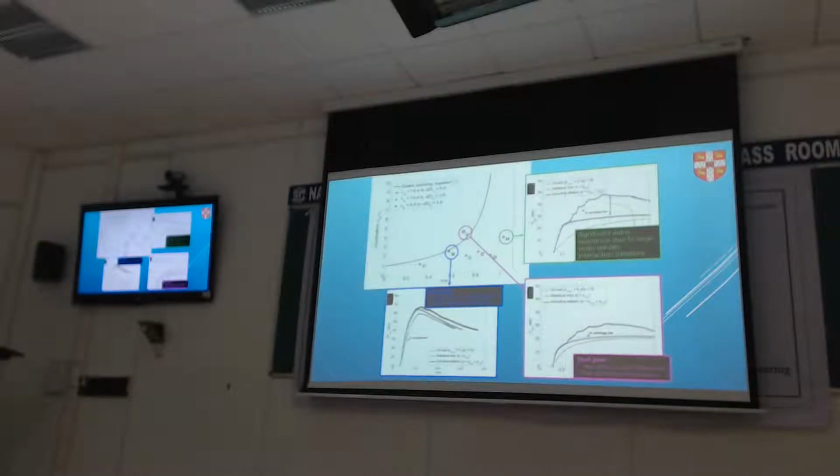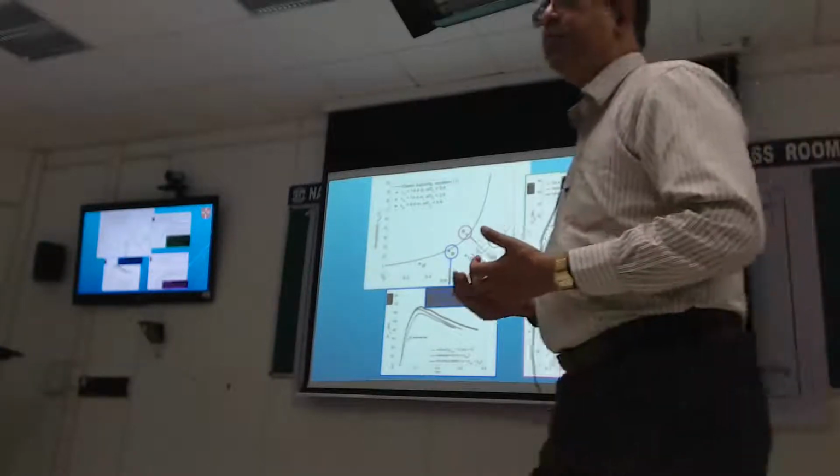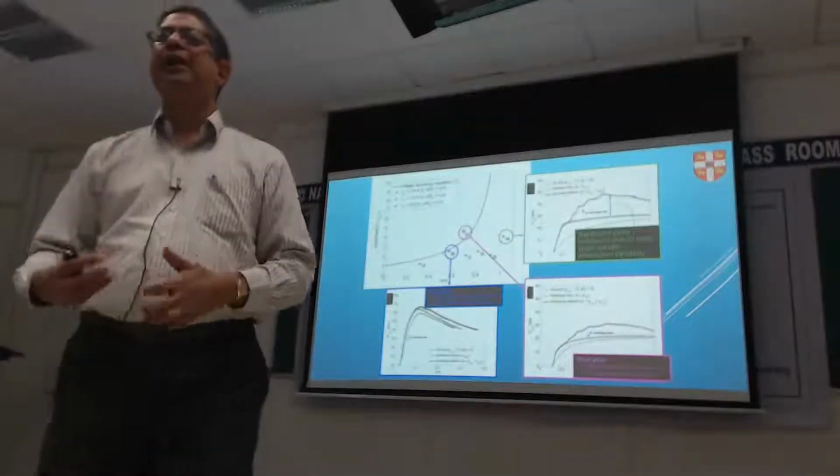So you need significantly extra resistance due to large strains in the soil while this pile-soil interaction is happening, and this is mostly coming from dilation. So if I take just the residual values, so this is the Euler line, and this is the residual values line, even that is not enough. The big peak needs to come in because of the soil dilation. So in a way, the more unsafe your piles are, the more you demand of the soil and the more it will try and help you.